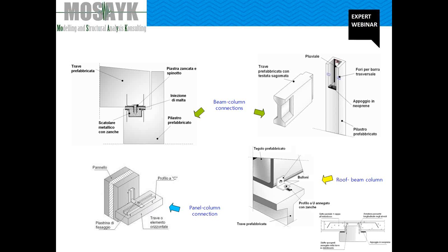Second type of connection is connection between beams and corbels in a multi-story structure. Dry connection with one or two vertical threaded steel bars fixed to the corbel by casting steel sleeves and tightened to the beam by nut and washer.